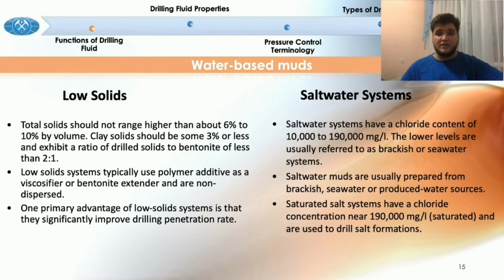There are low solids and saltwater systems. Low solids systems typically use polymer additives such as viscosifiers or bentonite extenders and are not dispersed. Saltwater muds are usually prepared from brackish water, seawater, or produced water sources.